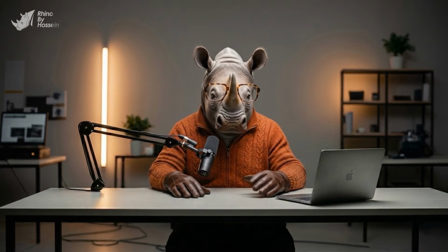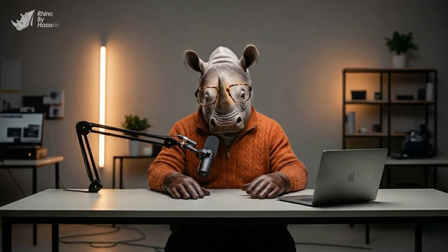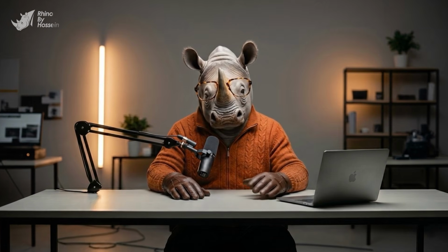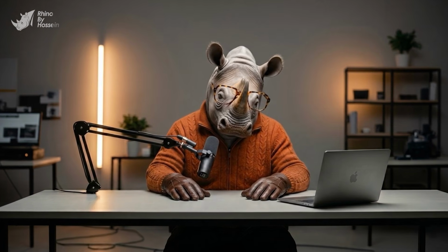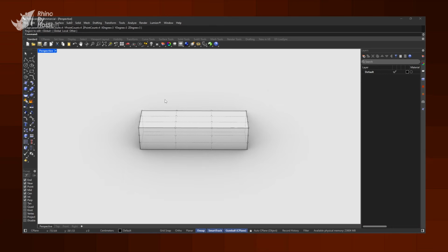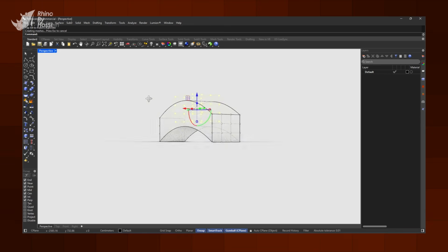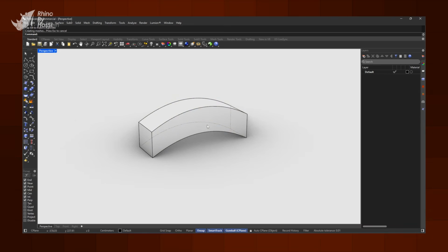In a way, the command line is a real-time feedback system. It tells you whether you're doing things correctly or not. But if you don't pay attention to it, you're essentially missing half of the most important information in your workflow. The solution is simple. Build the habit of briefly checking the command line after every command. It may seem like a small detail, but in practice, it prevents a lot of repeated errors and unnecessary confusion.